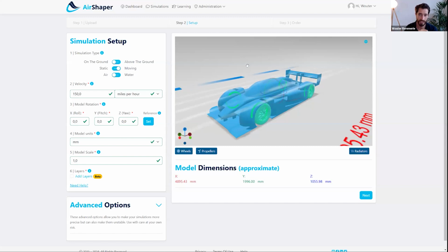And typically the industry technique is to shrink wrap a model, which is literally like you would create a vacuum bag, get all the air out of it, and this will wrap around your model, and this will close small gaps and holes. Now, a problem there is that it might work well in most cases, but in some cases you're closing gaps which aren't supposed to be closed, or the other way around. So this introduces errors.